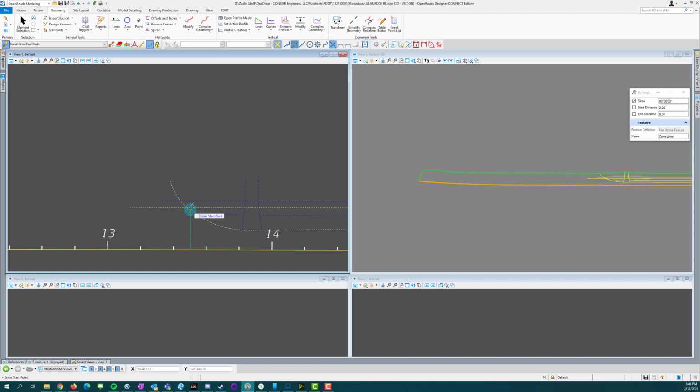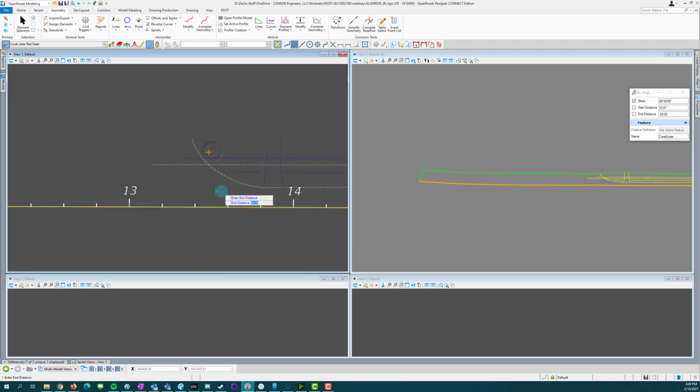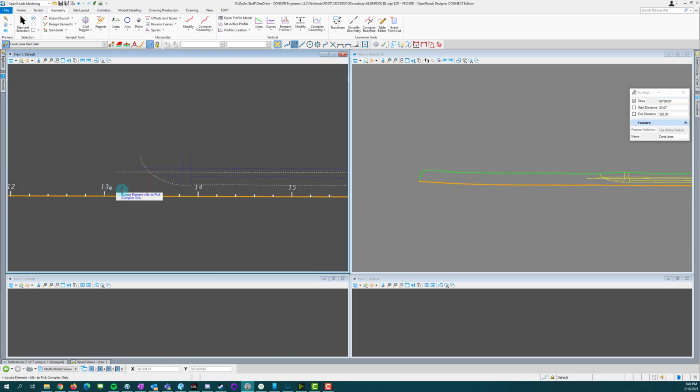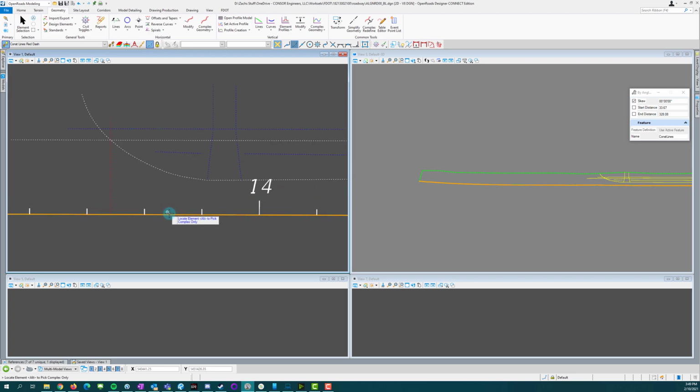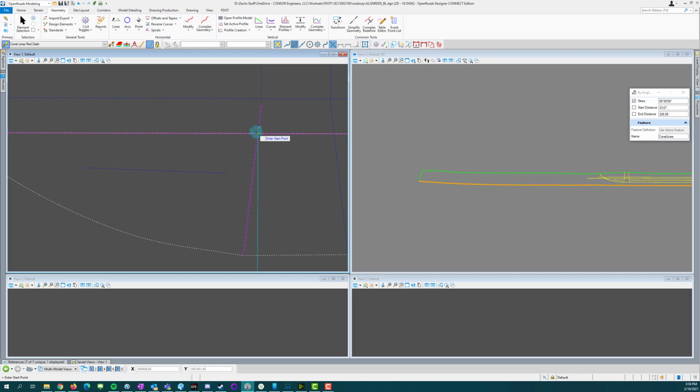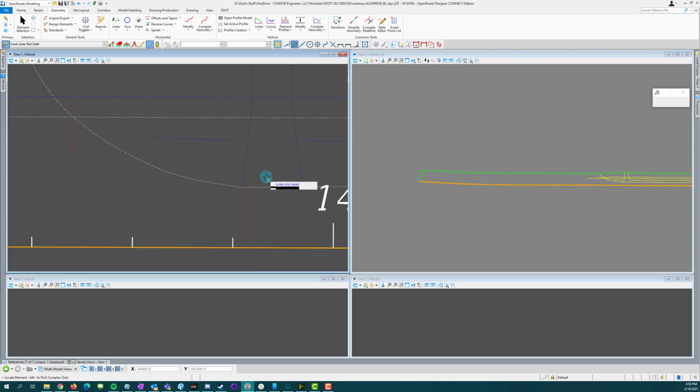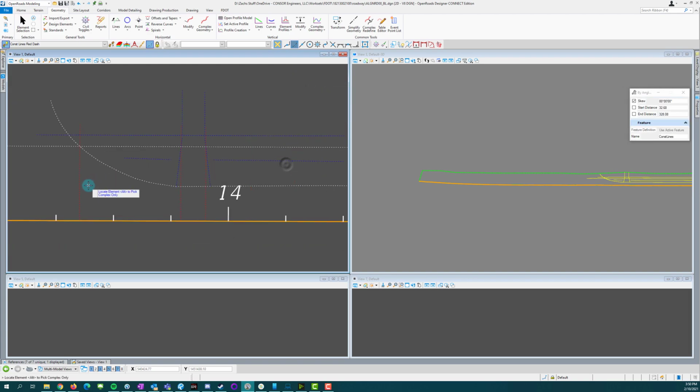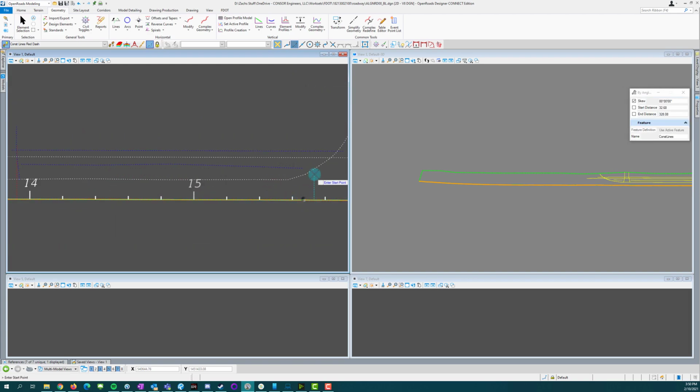So we're going to start with the back sidewalk profile. So we're going to snap to the intersection of this. Go a little bit past and then back to here. And then we'll probably want to do the intersection of the driveway. So this does take a little bit more effort to project this back to the center line, but in the end, it's going to save you so much time.